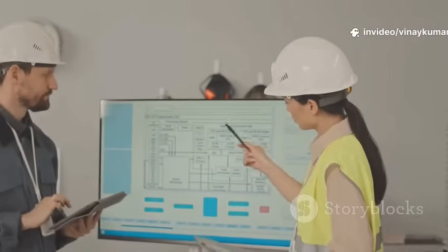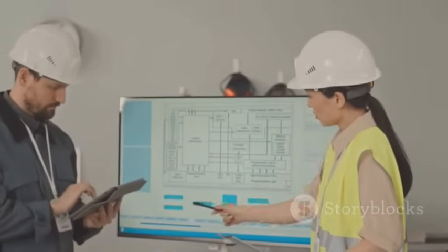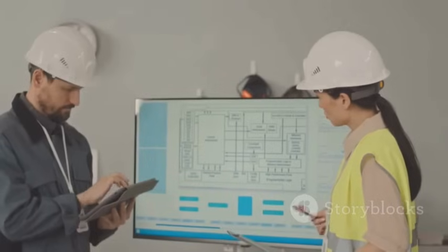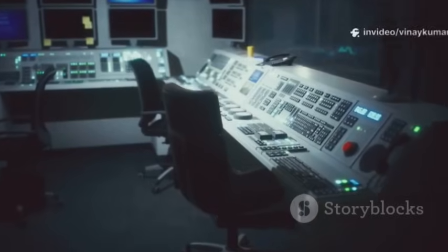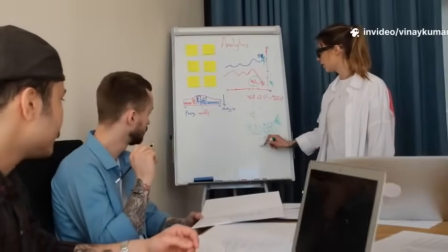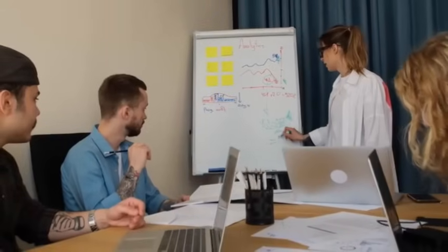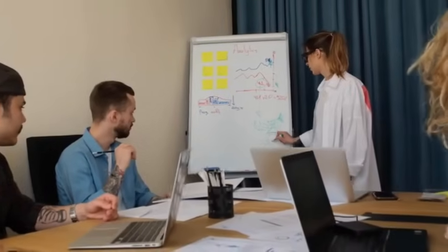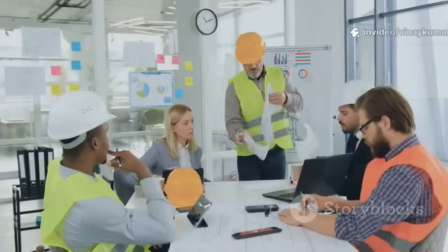It's easy to stop at operator error, but a good investigation asks why the operator made the error. Was the procedure confusing? Was the training inadequate? Was the alarm not noticeable? The investigation team must dig deep to uncover the systemic failures in the management system, the failures in the other PSM elements that allowed the incident to occur. This focus on root causes is essential for preventing recurrence.